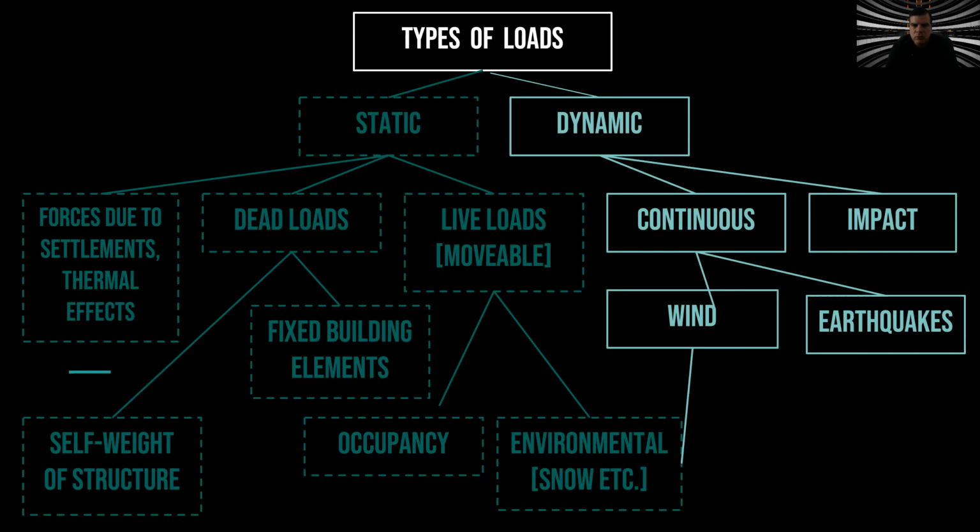The loads will be divided into types, statics and dynamic. Statics, the ones that do not move. Dynamics, the ones that move. Dynamic loads can be continuous, like a wind, like an earthquake. During some time, it will be acting and will be continuous, or can be impact. An impact load is dynamic, but it's very short. It's like when a car just hits a building.